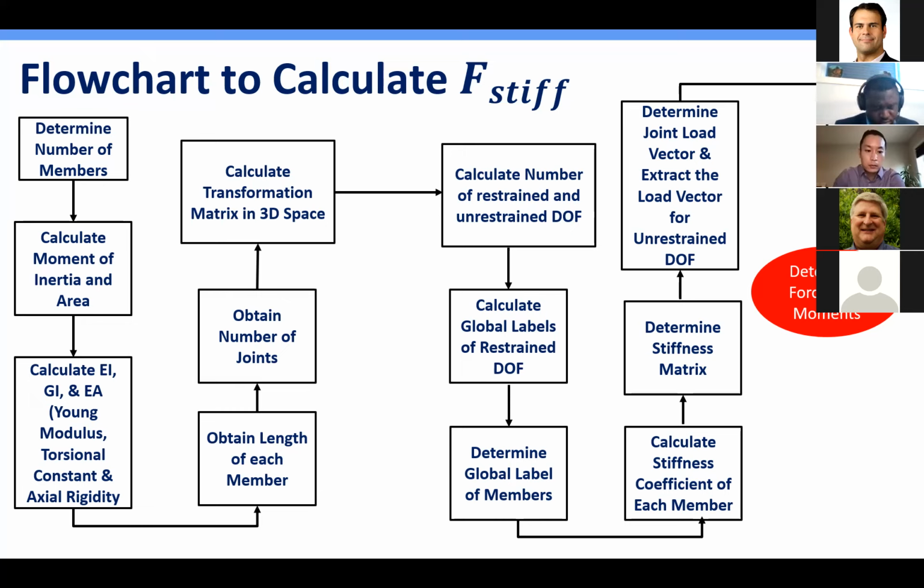Now I'll back up on the buckling part of it, but let's just talk about the extra contact force. Would it be possible to run the stiff string data and then come back and say the extra side force is less than 10% error? In other words, if the contact forces were less than 10% of the soft string values that existed already, might we even care? You could say, in this application I can run a soft string, and in other applications when I need stiff. I don't know, just kind of going down that.